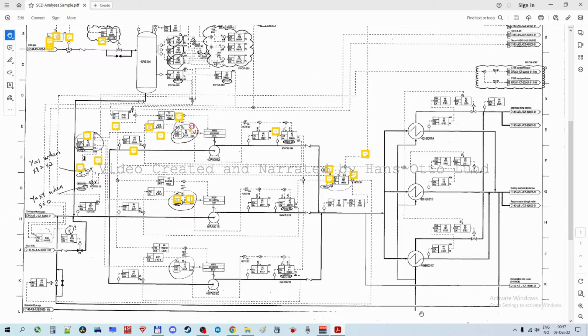So the seawater is entering here and draws heat from this cooling medium, and so the temperature of the seawater is higher going here, and it's just transferred to the seawater dump, which is often just overboard on the installation.